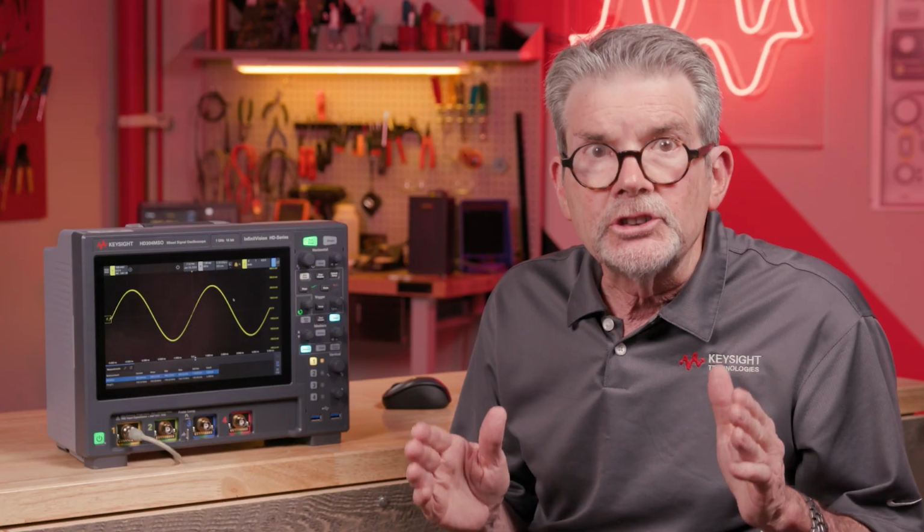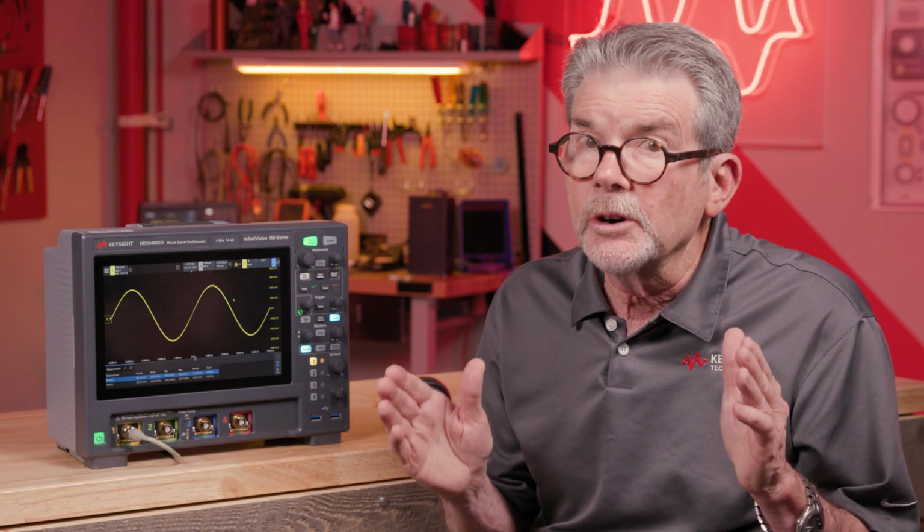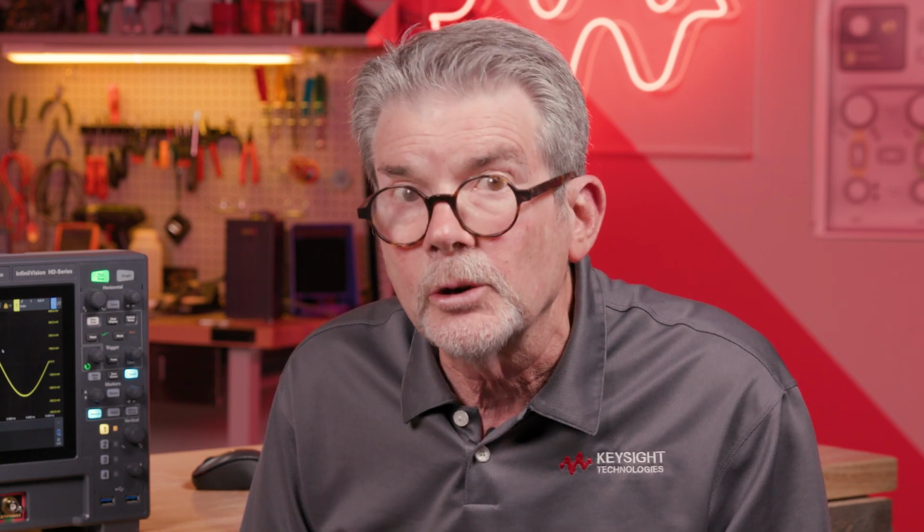But truth be told, the fuzziness of waveforms that you might be familiar with is not typically due to a limited number of bits of conversion. It's usually due to the noise floor of the scope itself. What you might be seeing is random noise introduced by the oscilloscope itself, not due to a limited number of bits in the ADC. This phenomenon can usually be observed on the scope's more sensitive volts per division ranges, such as 5 millivolts per division or below.